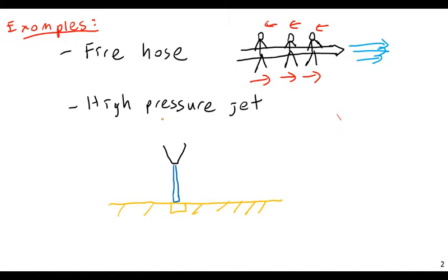So although it is a bit of a misnomer, it's not necessarily at a high pressure, because when I say it's a high-pressure jet, that's true, but only in the sense that it's high pressure while it's in the pipe. The moment that it leaves that pipe, it's only surrounded by atmospheric pressure. It's no longer being contained by the pipe, so it's at atmospheric pressure. What's really happening is this pressure energy is being transformed into kinetic energy, and that kinetic energy is what does the damage.